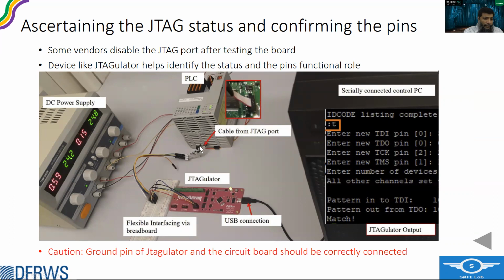One caution while using JTAGulator: the ground should match. So you have to manually match the ground before starting the JTAGulation.